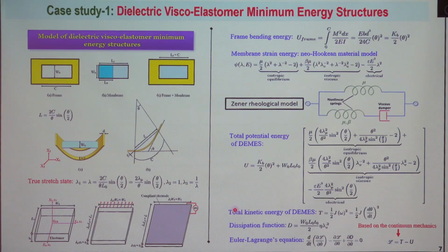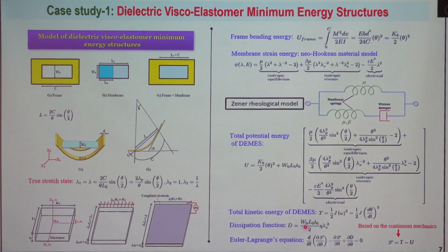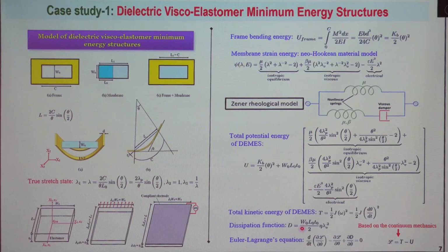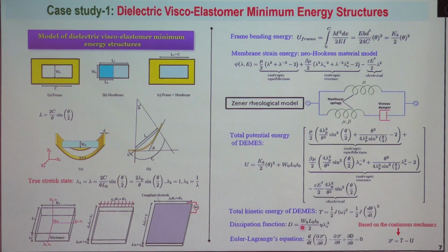Now, you have already seen that for considering the dissipation energy, different models are available. The Rayleigh dissipation function is the most commonly available one. So we have utilized the Rayleigh dissipation function here. You can get the basic expression or the derivation in different books or the notes I will share. Now, yesterday Dr. Prashant Saxena has also explained that the Euler-Lagrange equation of motion is the governing equation that you require. Basically, you have to develop the governing equation by using the Euler-Lagrange equation of motion. All the derivative part you have seen there.